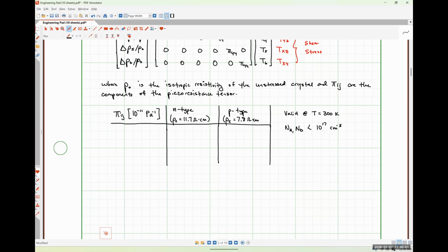So for the EE folks in here, I would interpret that to mean that if we have P-type silicon or N-type silicon, we can use these. But if we have P plus or P plus plus or N plus or N plus plus, meaning not super heavily doped, these are valid, okay? But if it's really heavily doped, we can't use these numbers, okay?